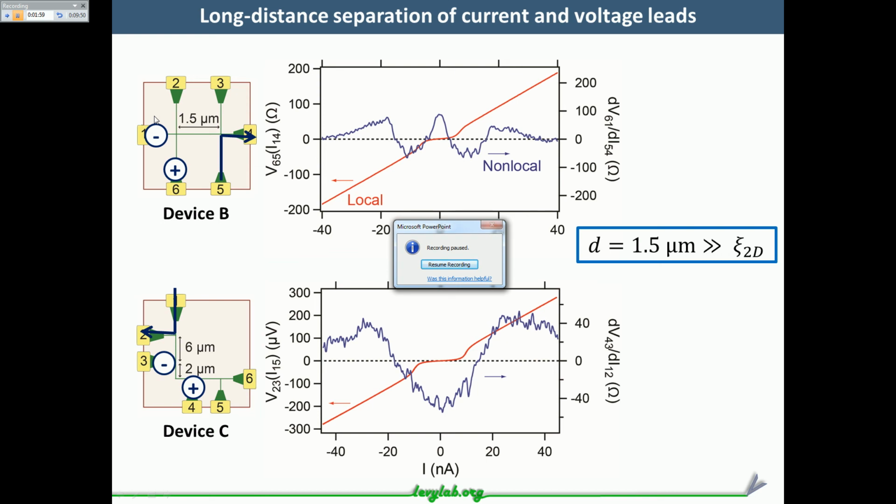Okay, well, I would still recommend swapping that because there's no other reason not to, except that at least now the data can be looked at and you can see that there's some peak in the signal and there's a sign change that happens near the critical current. So the same thing if it's well above the critical current, when it's plotted like this, they are the same sign.